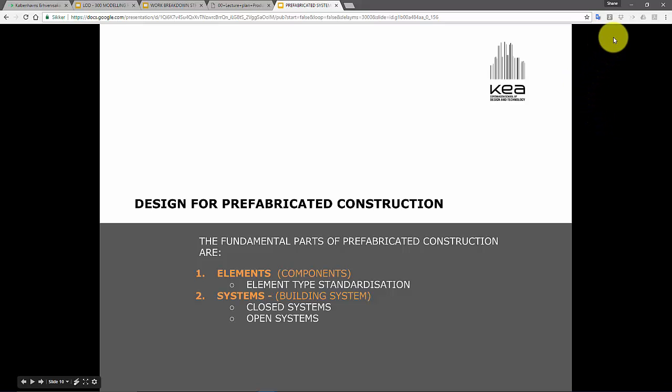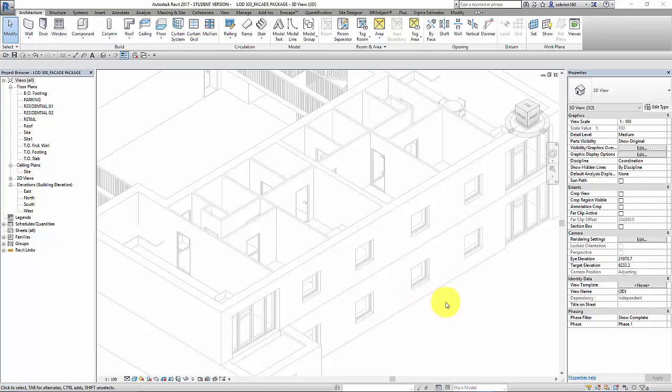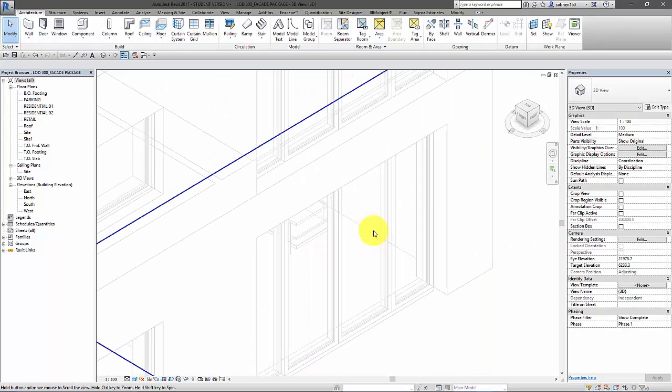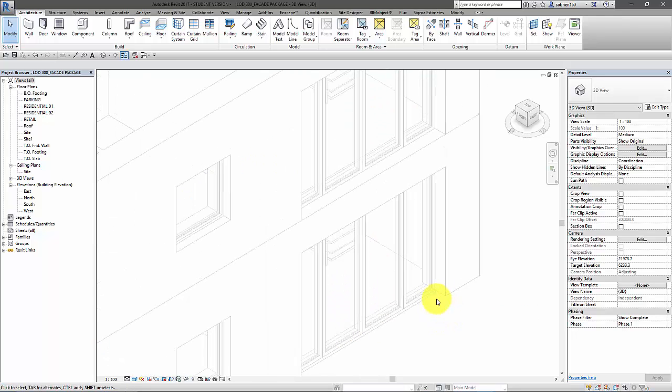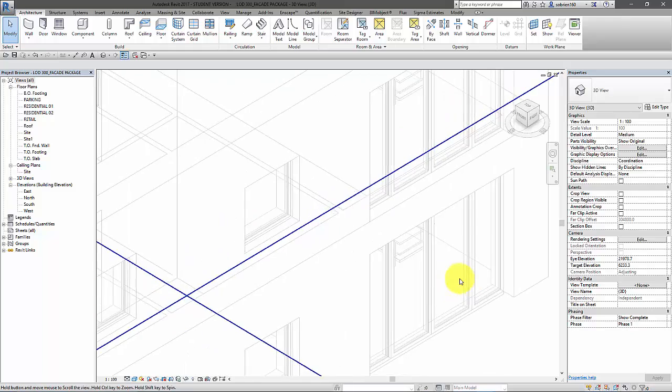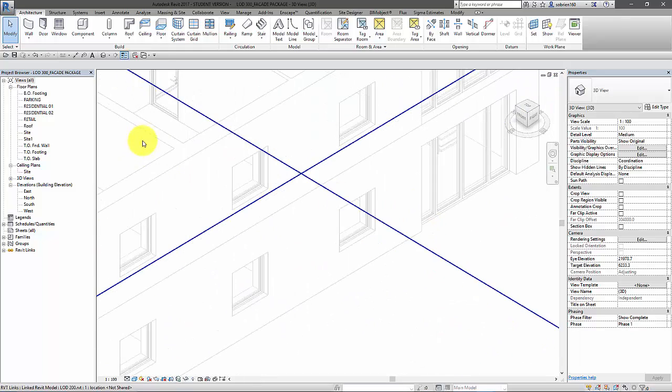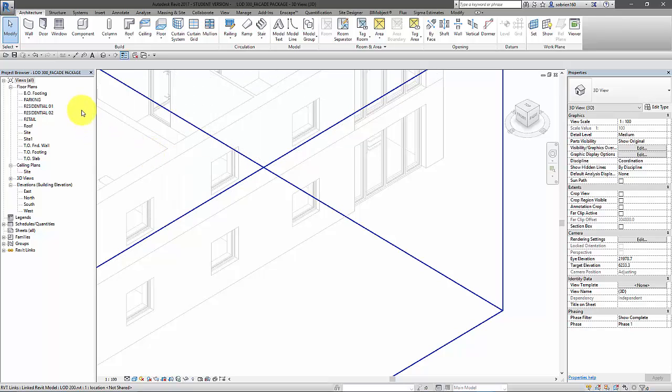But one of the tools in Revit that does that for you very simply is the curtain wall system. Now, usually a curtain wall system is for stuff like this, where you can just make a very simple glazed element. But it has a lot more power for doing many, many things than just these glazed elements. So let's just have a look at how we would use it.